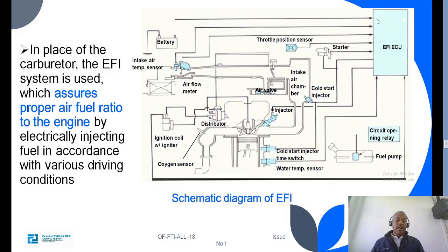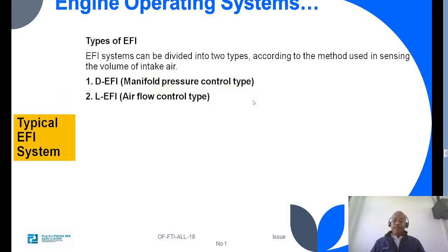So these sensors are the input for the amount of air flowing through the air duct or air intake system. So the computer calibrates the injected amount of fuel based on the air intake. And there are also other corrections to maintain the proper amount of fuel injection.